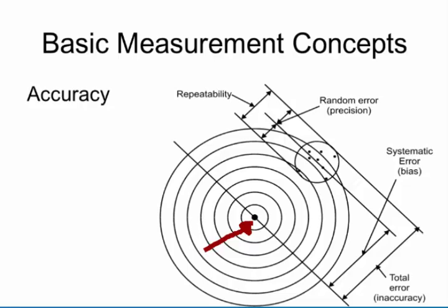Okay, so it is the value that happens out in the field. Now, through a series of electronics and mechanical interfaces, there's a type of error built into it, referred to as the systematic error. And that systematic error is really a function of how the sensor is made, how the sensor is installed, how it is actually put in the actual instrumentation, or the actual process.